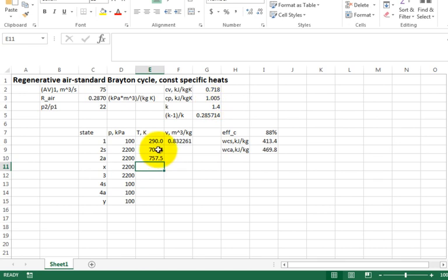So if it would have been 100%, it would have come out at 701.4, but because efficiency is 88%, it comes out at 757.5. It comes out hotter. I look at it. I'm comfortable with it. I don't think I have an error. I can play with this. Maybe I put it at 98%. See, the temperature is much closer. Okay, how about this one? 99.99%. 100%. Change it back to 88%. Whoops, escape. Get it in the right cell. 88%. And there we are.